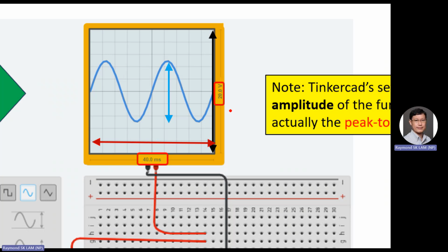All right. So you have 20 volt and 10 divisions. So 1 division is how many? It's 2 volt. So now you look at the timeline here. From here to here, how many divisions? This is 1, 1, 2, 3, 4. Then this one half, the other side half. Right. So altogether there are 5 divisions. So 5 divisions, how many volt?